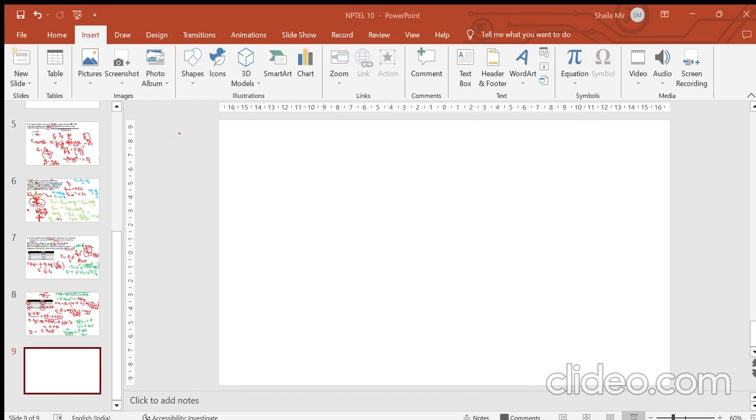These dislocations have a very important role to play in a material. One important role is the work hardening effect. What is work hardening? It tends to give high strength materials, because these dislocations prevent any deformations from occurring in the material. Deformation and dislocations are directly related. If you have a very high dislocation density, there are a large number of defects inside the material, and you can have a higher strength in the material.